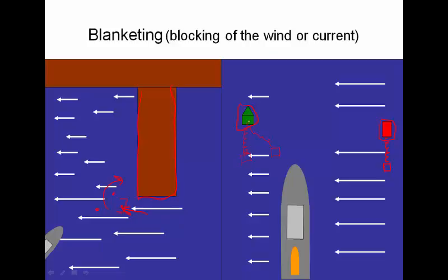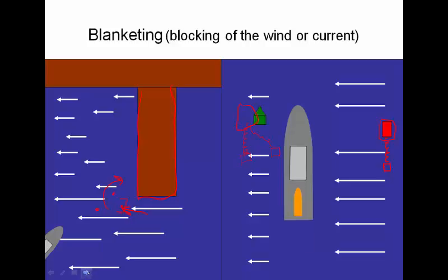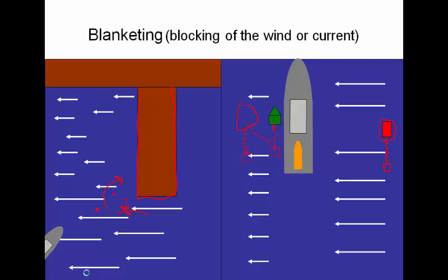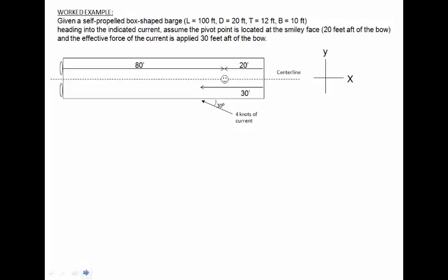So what happens as my vessel moves further up the channel? Well, it starts to mask the wind, and the buoy starts to bring itself right above its sinker because it's not feeling any of those forces due to the wind. If I'm not careful, and this comes back to where it wants to be, and I don't predict this happening, I could actually have the buoy strike my vessel, and that's no good.